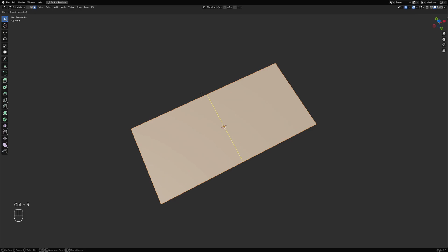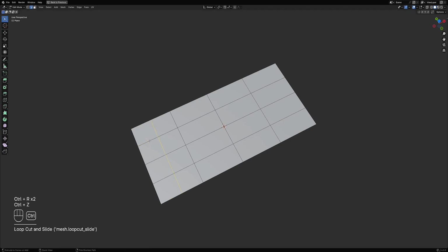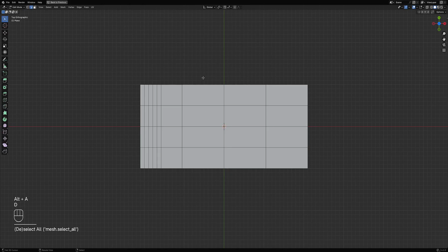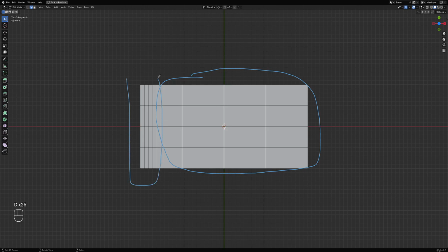So for example, if we create this kind of topology, which is a mix of relaxed and more densely packed areas with faces, then with this kind of topology, the face groups generated in this area will be more relaxed and bigger compared to the area right here, which has more densely packed faces.